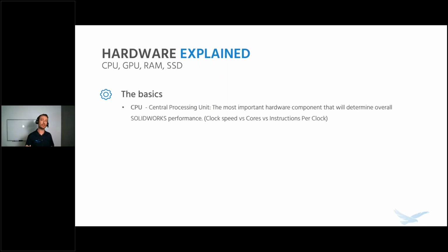And also the third specification that you're not going to see listed on any spec sheet anywhere from Intel or AMD, but it's important to mention, and it stands for IPC, instructions per clock. What that basically boils down to is, in a given 1 hertz, or however many clock speed that processor can run, how many instructions can it handle in that 1 hertz? So every year when new processors come out, the chip companies say, well, we've increased our IPC by 10% or by 15%. And you're never going to see a hard number associated with it other than that percentage.